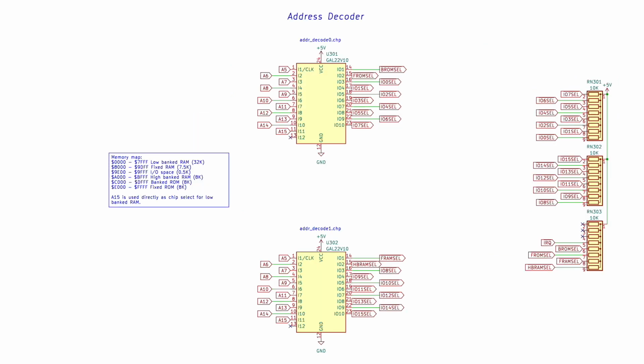And here's the address decoder schematic. I know it's not terribly exciting since it's just two chips and all the action is really inside the GALs. But I did want to point out that the address decoder takes the output of the address buffers and not the signals directly out of the 6809. This will actually become important later, specifically when I talk about that dimmed out chip from the previous diagram.